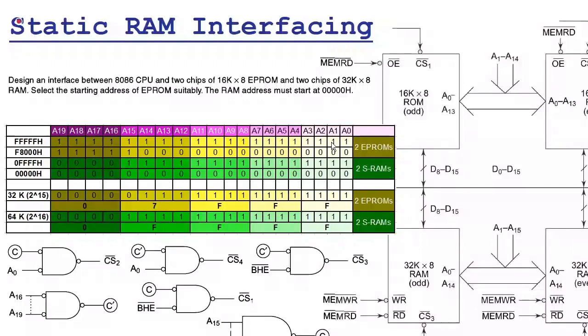The same thing happened in 8085 also, but that was for a different reason. The little endian fashion was followed there, and the transfer took 2 machine cycles when transferring data from the microprocessor registers to the stack, because the stack always operates in a 16-bit or 2-byte fashion. So there it was not by construction, but here it is by construction. This fact should also be noticed.